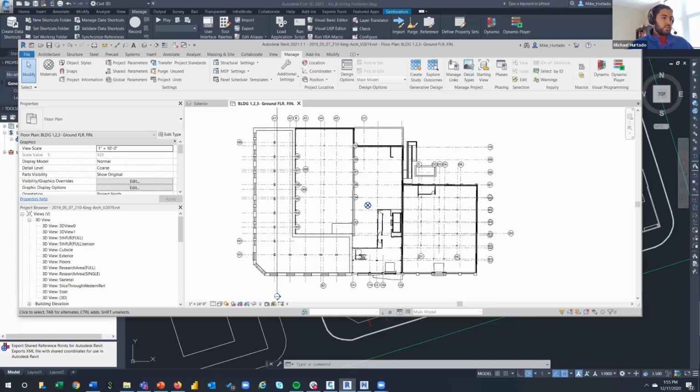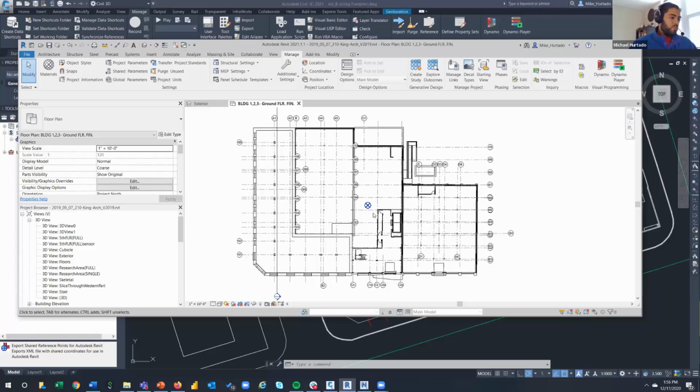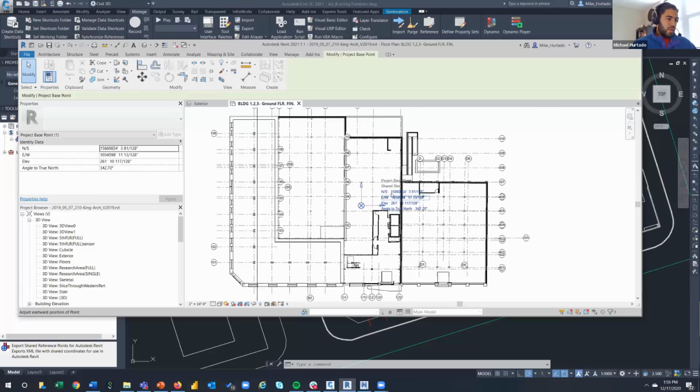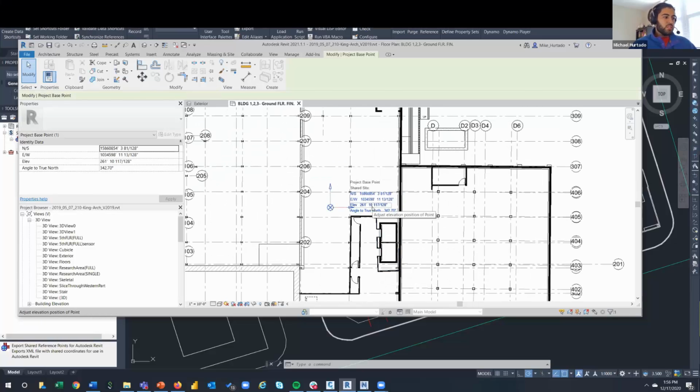One of the quick tests that I like to do, by the way, for anybody that noticed that, oh boy, this is where my Revit IQ is lacking. The project base point went away. Not that it went away, it moved just to have that information, but the project base point is still here. And it kind of filled in this information automatically for us based off of the information that was in that XML.